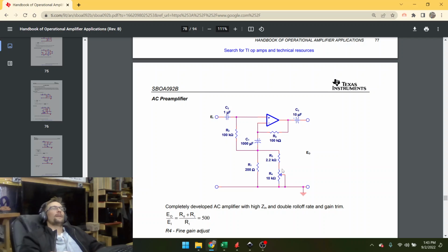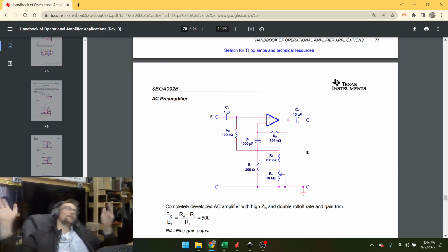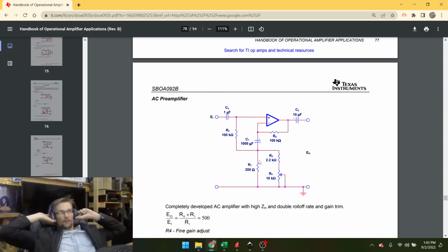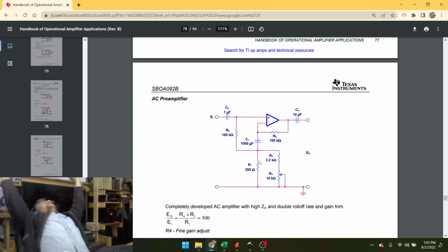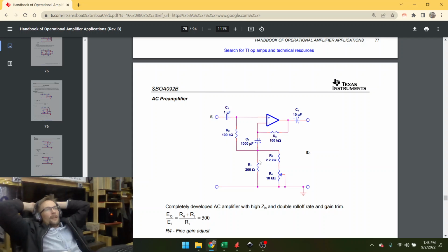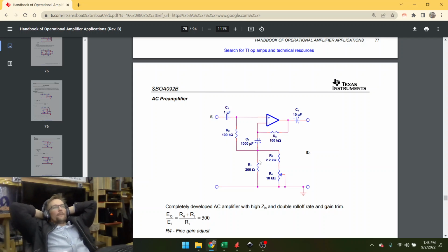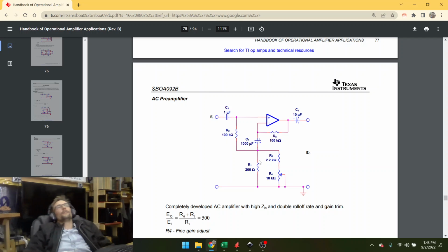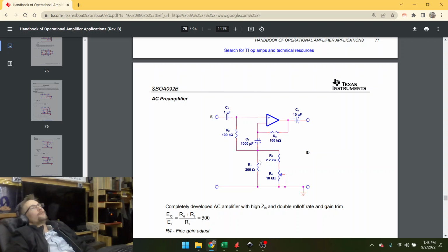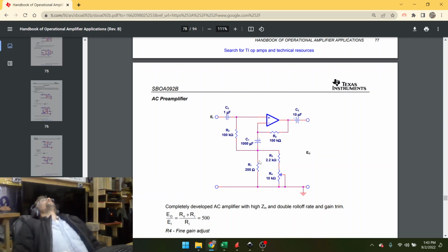if this guy goes to maximum 10K plus 2.2K, it parallels to 200, so it's really only 190 something, right? And then if you send it to the minimum, so that 10K looks like a 0, then you have 2.2 parallel to a 200, so it's probably like 150?